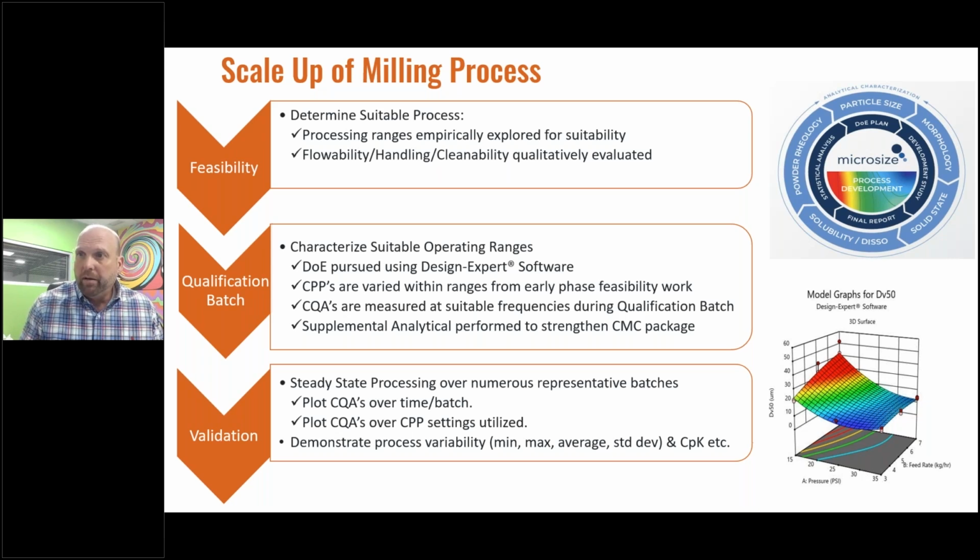Yeah, the qualification batch can typically be either a continuation of empirical design using the practical experience over 30 years, or doing a full DOE assessment if material allows, and getting contour plots developed for the CMC package. And to that particle size and dissolution, there's always the ability to confirm the crystallography, or the crystallinity rather, understand the rheology of what we're making, and do all of that in-house.